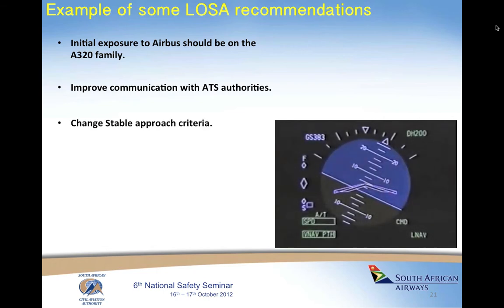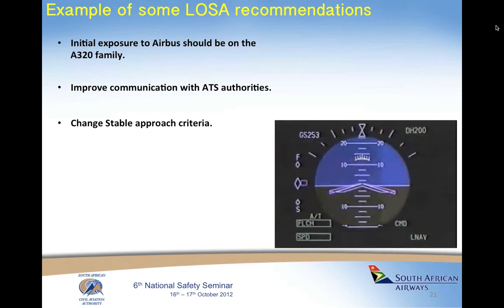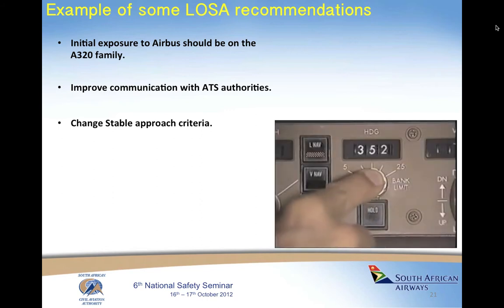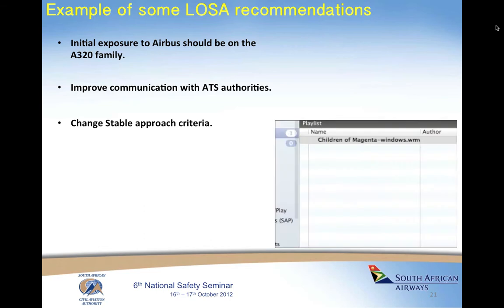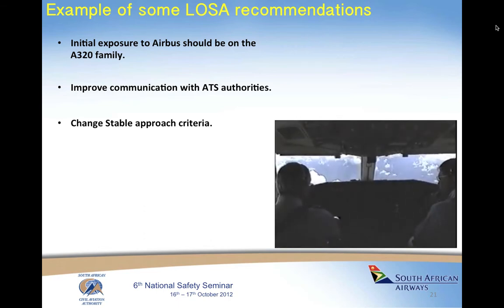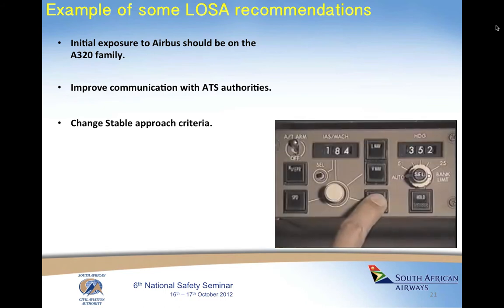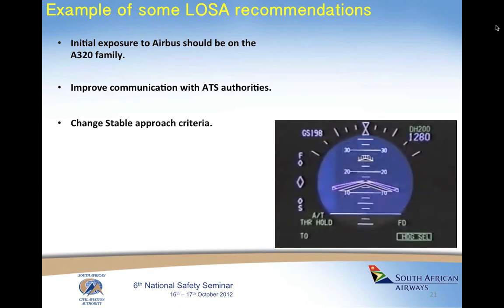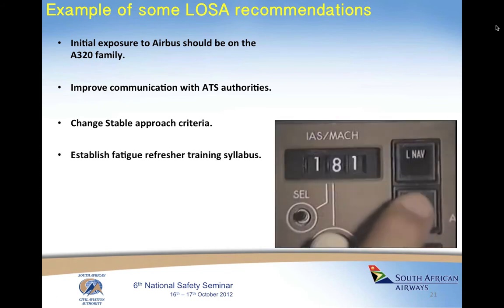Change the stable approach criteria. In this case, criteria create a stable approach risk management profile which allows the go-around decision to be analyzed by the crew at 1,000 feet RA, or radio altitude, and finalized by 500 feet. So the LOSA actually picked up that to optimize the operation, reduction in the stabilized criteria would be still within the safe envelope. Establish a fatigue refresher training syllabus.